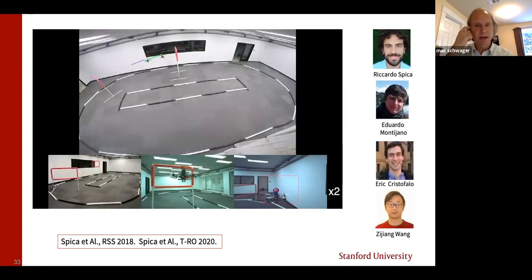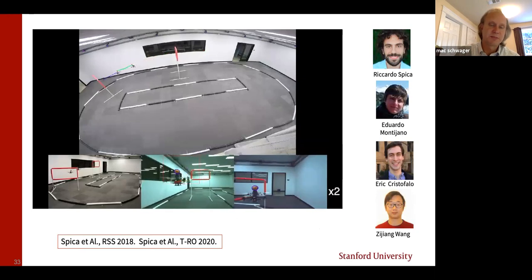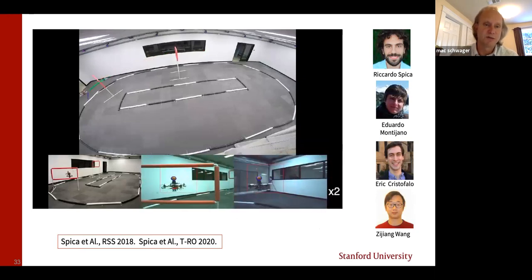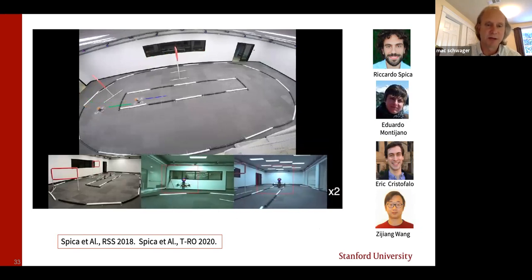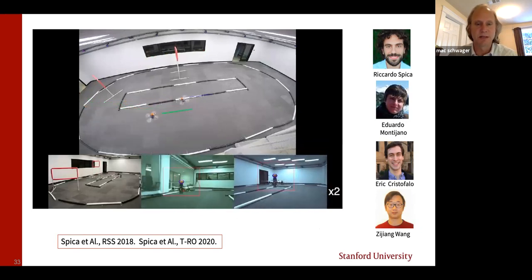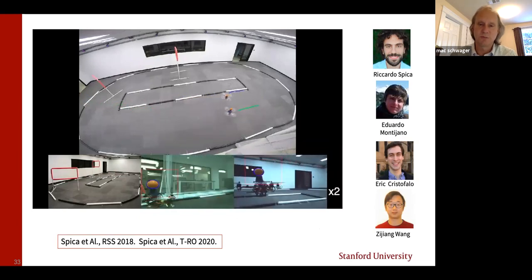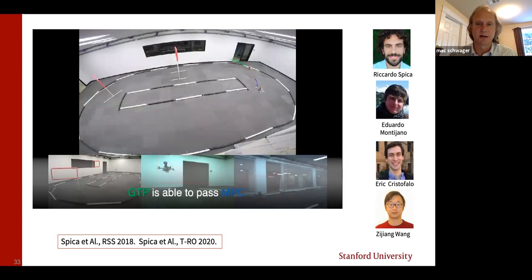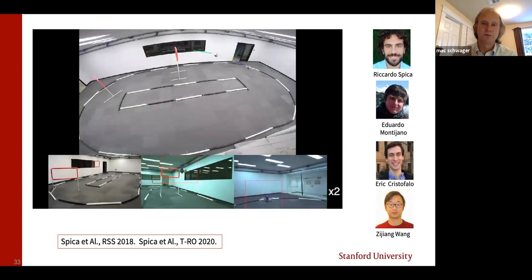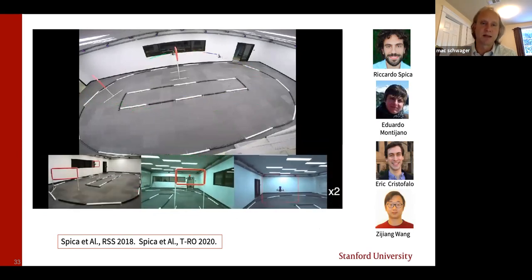And so this is what you see happening here. The plan that's being optimized for each drone is in green and blue in the video. The green one, as I said, is using game theoretic planning. The blue one is not, it's using just MPC. In other words, it assumes that the green guy is going to do something very silly, like keep moving in a straight line at a constant velocity, and plans according to that hypothesis.